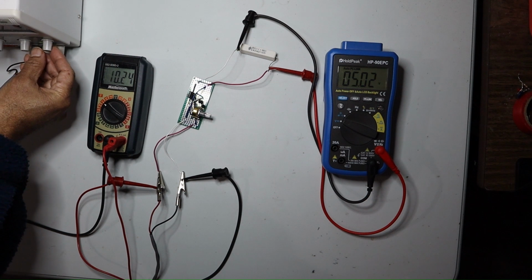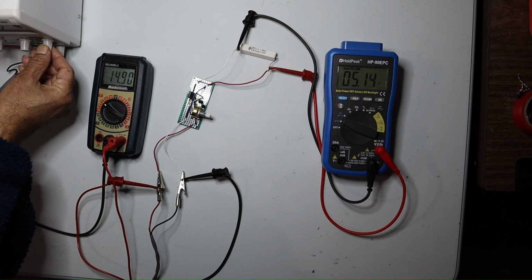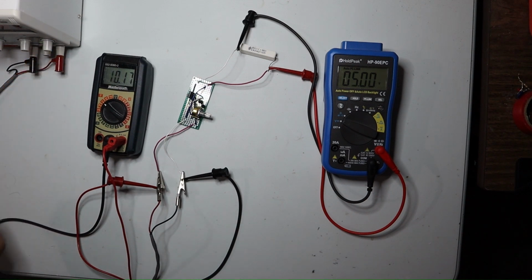And now I am trying to increase or decrease the input power supply voltage. You can see that as the voltage goes up, the output voltage goes up a little, and as it goes down, the output voltage also goes down a little. Beyond 6 volt, you can see the voltage drop. The output voltage will go down rapidly because it will lose total control of the regulation, and it is back to 5 volt at 10 volt input voltage.